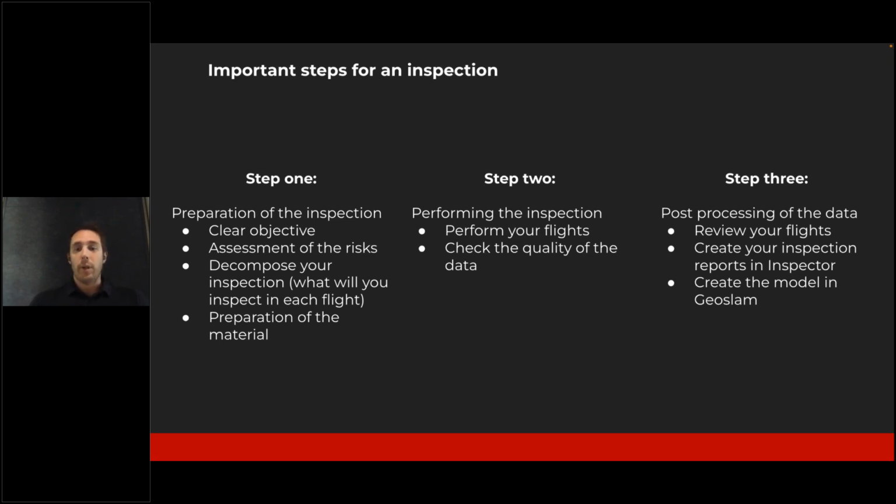And the third step is the post-processing. So where you can download your data, review your flight, create your inspection report, and later on, if needed, create your model in GeoSLAM.